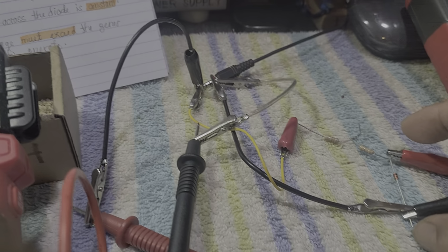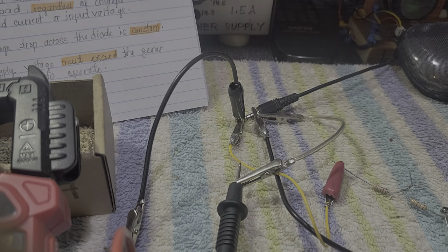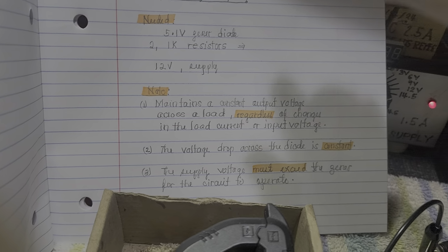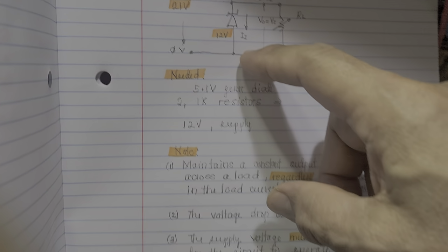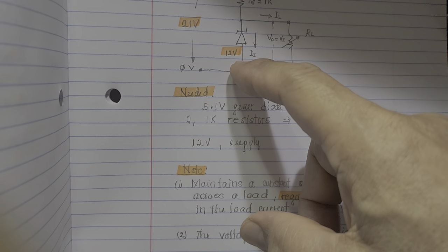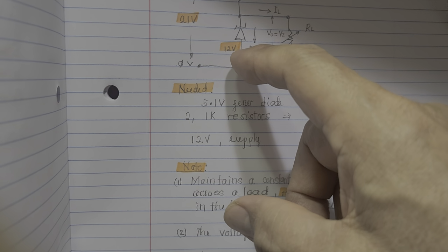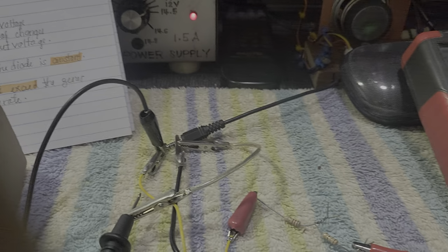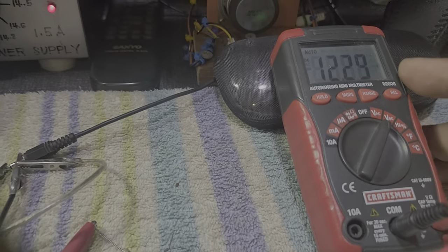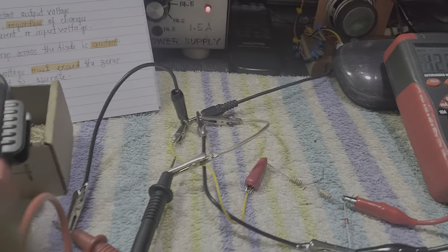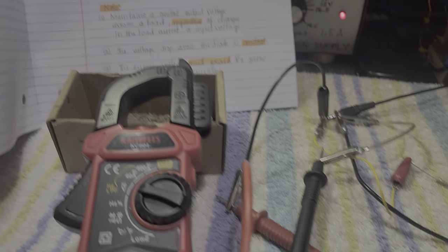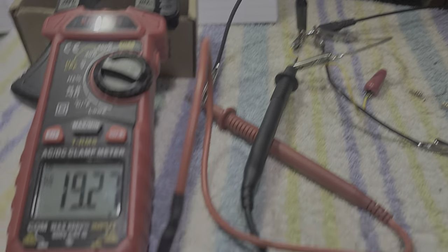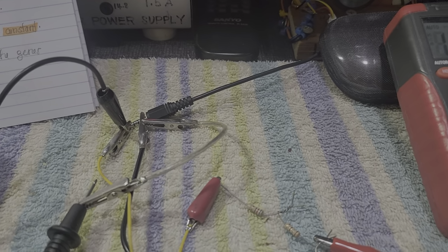Like what I said, if we try to check the validity of the voltage across the Zener diode, whether it is really acting as a 12-volt regulator, because this Zener diode is a 12-volt, the voltage output of this one should be 12 volts. And what comes out as per measurement is 12.29. That's the actual assembly of a Zener diode acting as a voltage regulator.